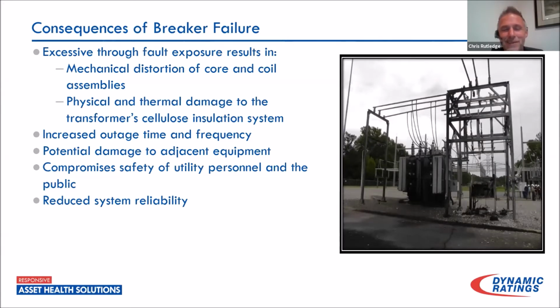So this was not indicated at all with the power factor test. We had just seen a small change in capacitance. We actually had to run an SFRA test at that point, or I had them run one just to see what it looked like, at which point we could see the change that had occurred. So we need to limit these through faults by these slow operating breakers. And with that, we can reduce our outage time and the frequency of these outages.